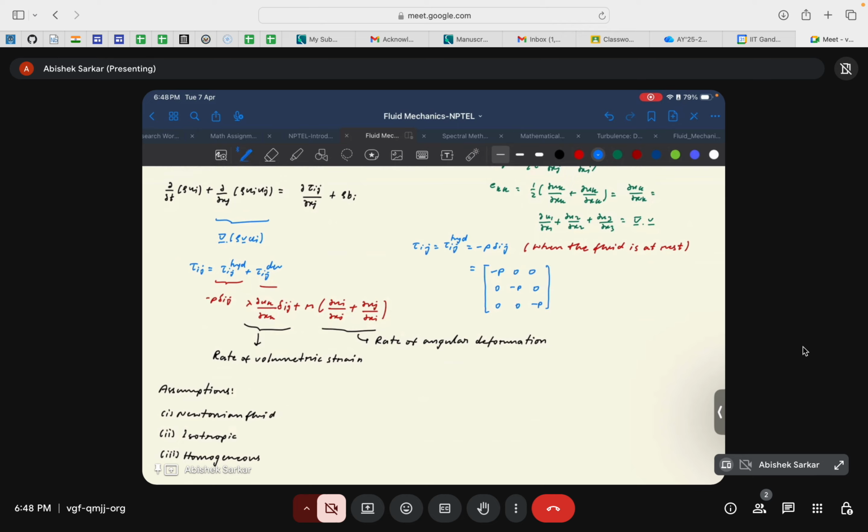You might point out an example like if there's a pressure vessel, then pressure tends to be acting outward, but that's not the case, because even if it's a pressure vessel, the pressure acting on the inner surface of the pressure vessel is again acting in the opposite direction to the normal vector for the inner surface of the vessel.